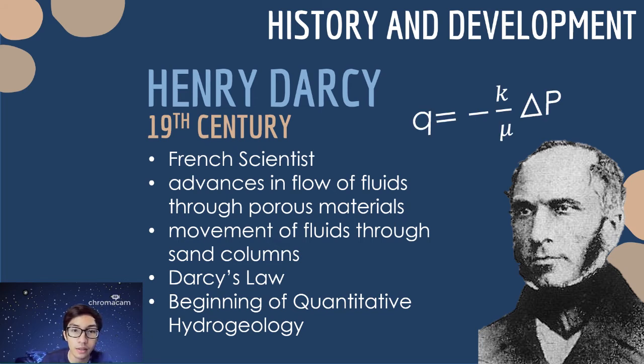It says that the discharge rate Q is proportional to the gradient in hydraulic head and the hydraulic conductivity, with the general formula in the presentation, where K is the permeability, Mu is the dynamic viscosity of the fluid, and delta P is the pressure drop. Darcy's work is also considered to be the beginning of quantitative hydrogeology.